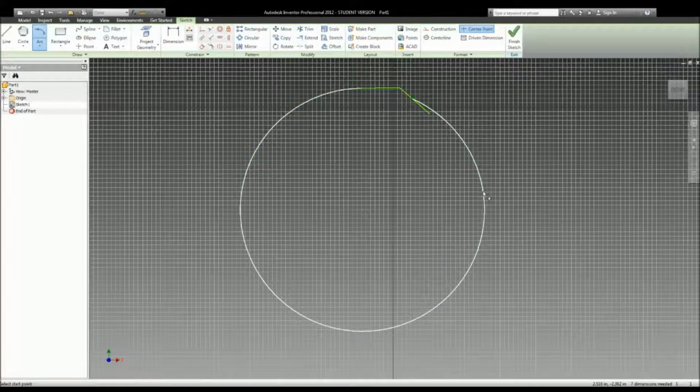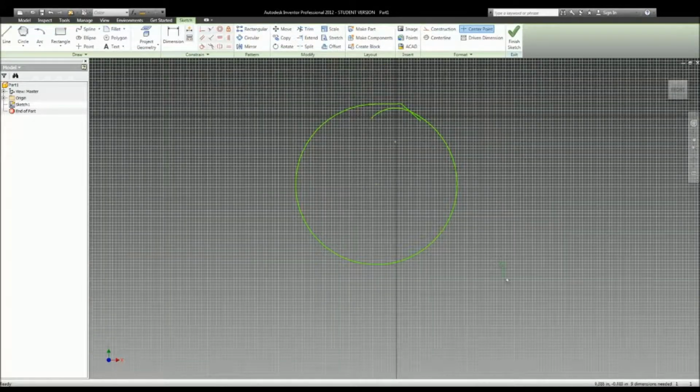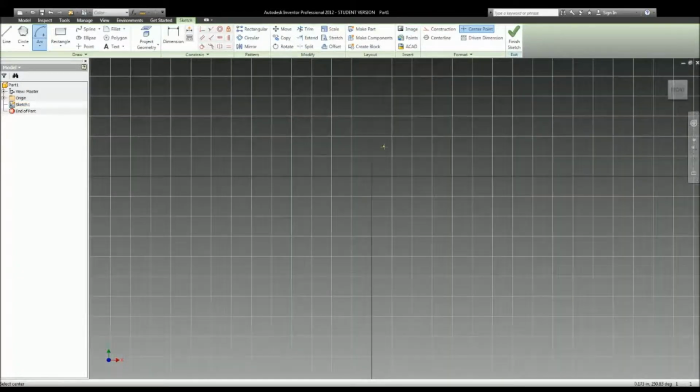It's a little finicky sometimes because what you need to do is actually probably change the values that you want as it goes. I personally don't like to play around with the tangent arc. I honestly don't play around with the arc too much because there's a better function to use for it, specifically fillet, and I'll be going into that here in a second. But if you were to draw an arc, you probably want to go off of center point or 3 point. Center point is very similar to how you drew the circle.